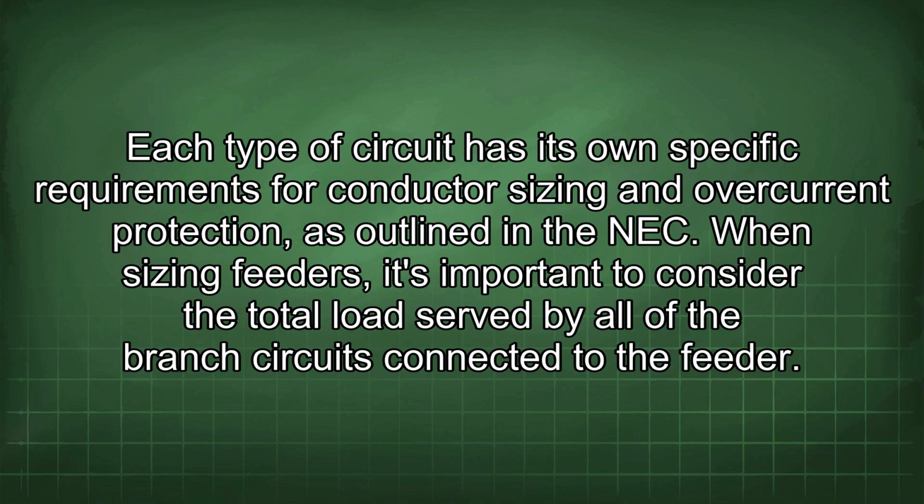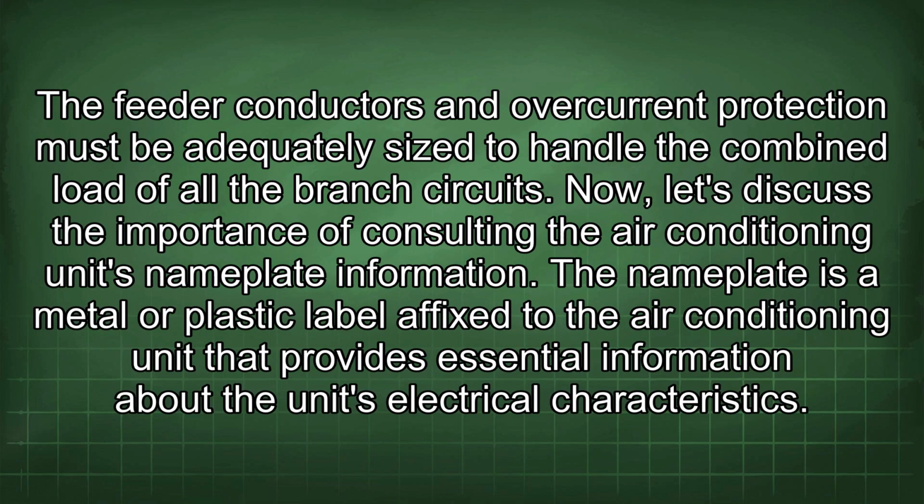When sizing feeders, it's important to consider the total load served by all of the branch circuits connected to the feeder. The feeder conductors and overcurrent protection must be adequately sized to handle the combined load of all the branch circuits. Now, let's discuss the importance of consulting the air conditioning unit's nameplate information.